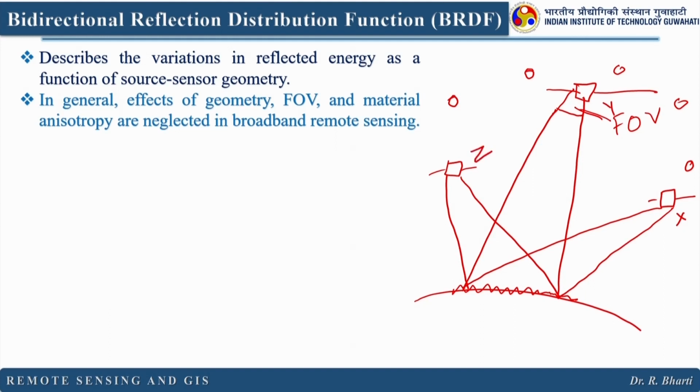If you want to use 3 different satellites for some application, what do you have to do? You have to take care of the time when this particular image was captured and with what look angle. So, if you draw a vertical perpendicular from this surface, what is the angle, right.